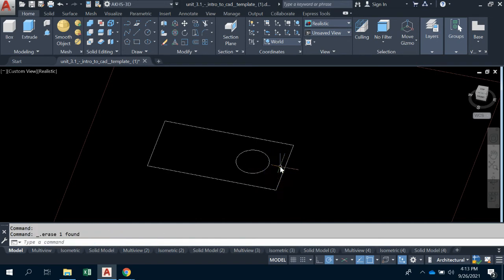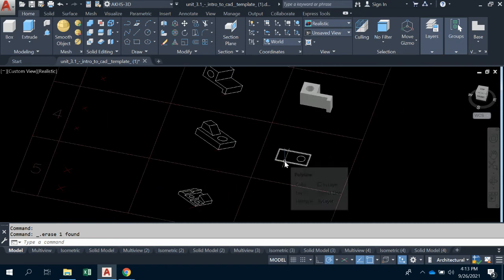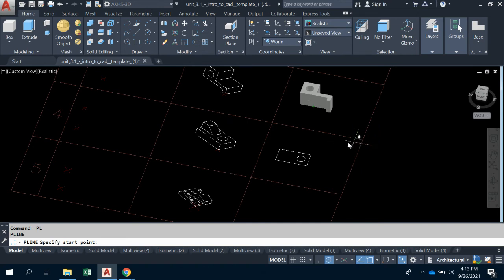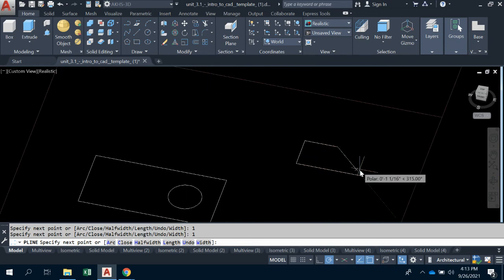Select this polyline and delete it. Use the delete command, not the backspace on your keyboard, in case you forgot. And then we can go ahead and draw this little profile up here as well. So PL, enter. We'll save that inclined plane for last. I'm going to start here on the right side and go left for a distance of 2. Give it a height of 1, 1 along the top as well, and then connect for your last step.